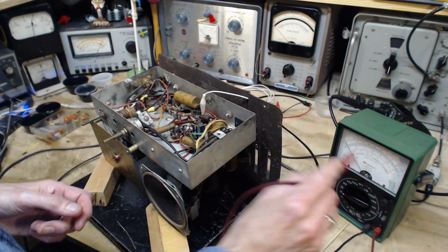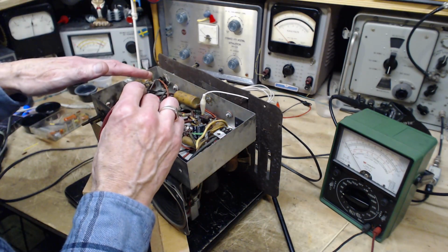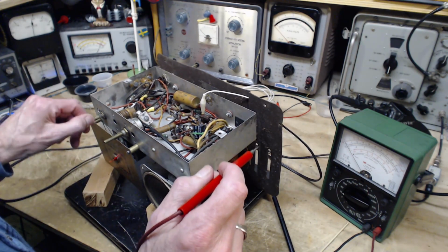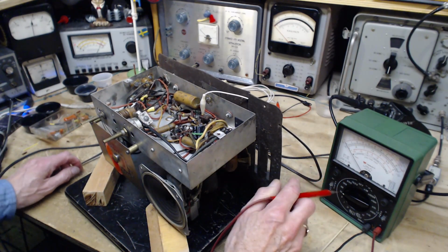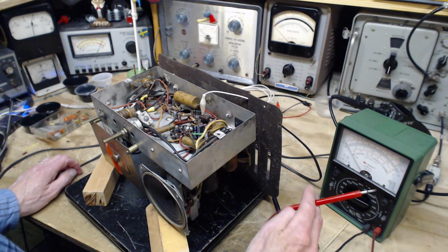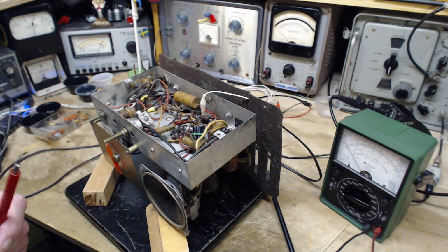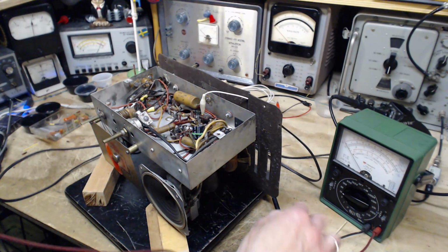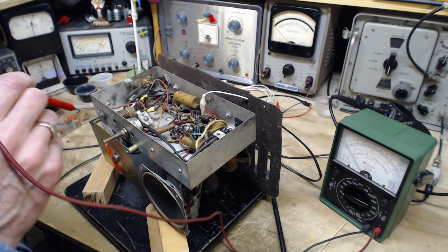So I think it can be said, putting this meter on is affecting the circuit enough that whatever I'm measuring has to do with a state different than what we hear when the meter's not on. So don't really know for sure what I'm getting there. This is a very high impedance meter, about 10 megohms. But I have another one which is much higher. But maybe we will try that out. Now it could just be these long leads being used here. I have this one clipped back to the B minus point.